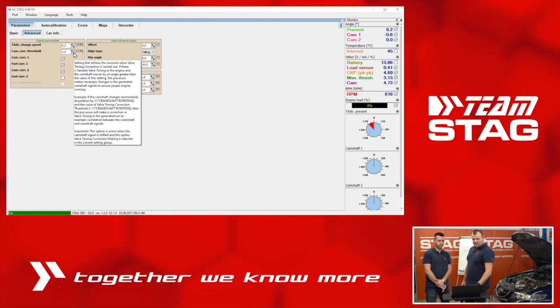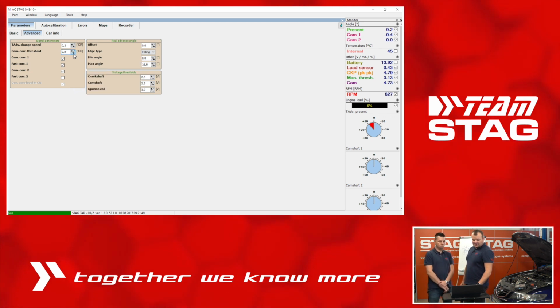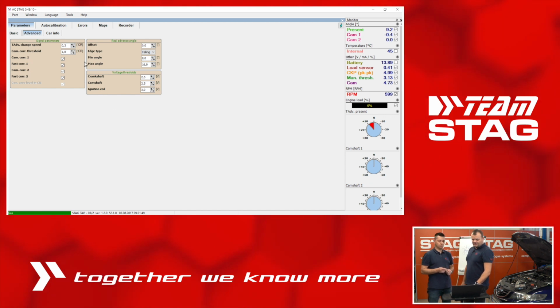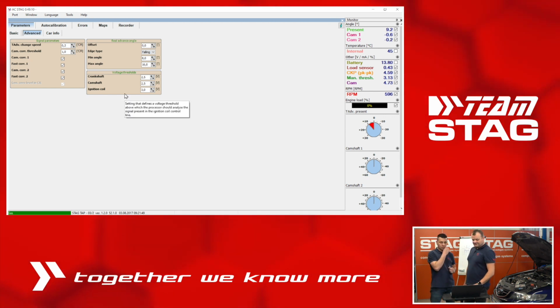And then you can also have an influence on the algorithm. You can add or reduce these algorithm factors so that the end result is to reduce the jerking totally and forget about any issues. It's working also with the first cam and the second cam. In case you meet an engine with variable cams, not only on the inlet like in this engine, but also on the exhaust cam, you have the option to use the corrections for both cams to resolve any issues in relation to variable cams and variable camming.